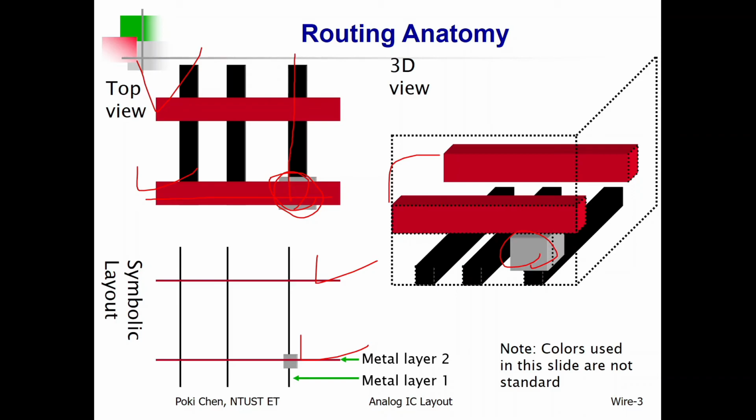here, all right? But sorry for that, because this part was not drawn by myself. I just got help from the other professors. So what's going on here? Actually, the size of the via should be much smaller than this. Okay, as I told you, for example, this is the top layer and that is the bottom layer, right? So for such kind of overlap area, your via or contact should be smaller than the overall overlap area. That is what I mentioned, maybe in chapter 2 or chapter 3. Okay, anyway, all right. So this is not to scale. 这个不是按照一般的尺寸来画。一般来讲，metal 1跟 metal 2，它中间或任何两层中间的那个 contact 或是 V 它的 size 一定要比上下层还要小。这我当初就有跟各位讲到过了。Okay, that's it.